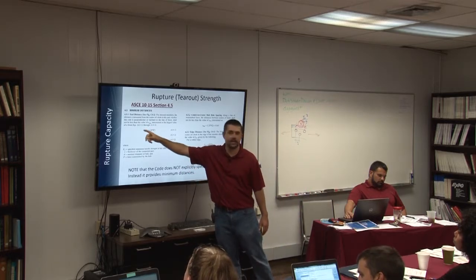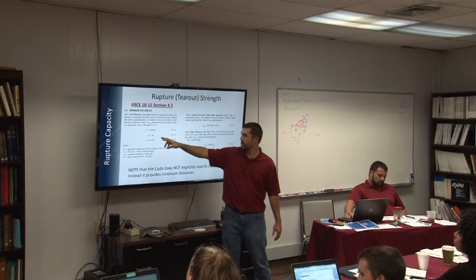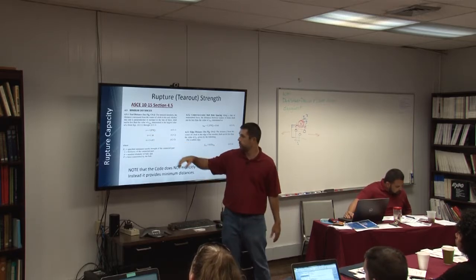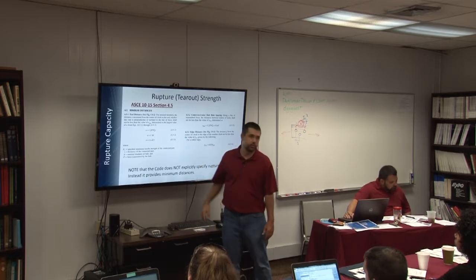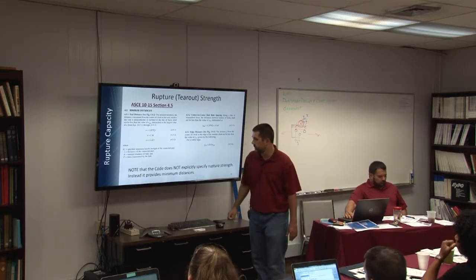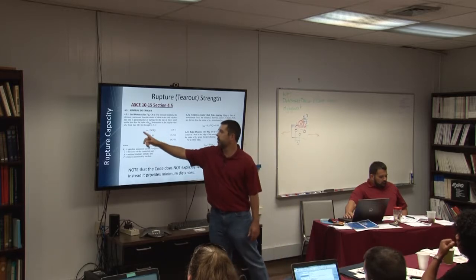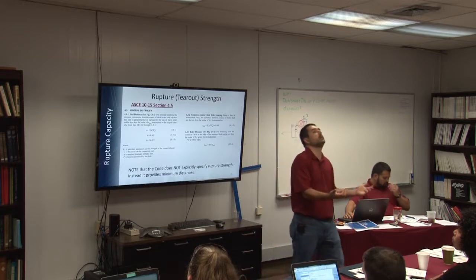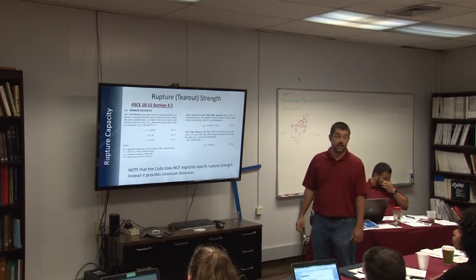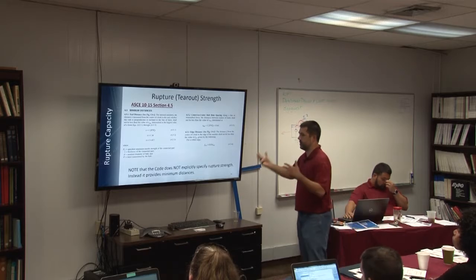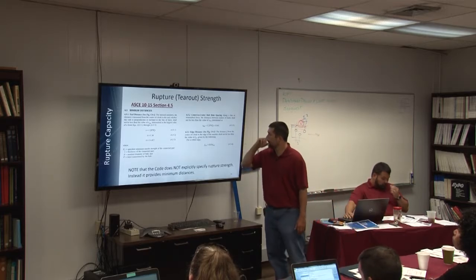Or there is one that's somewhat tied to load. So it's basically 1.2 times the load in the bolt divided by the rupture strength of the material times the thickness. But that's essentially the 3 equations that control end distance. How you must meet these end distances if you're designing new towers. Again, this is going to be this kind of interpretation deal.